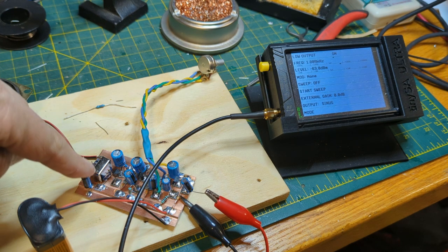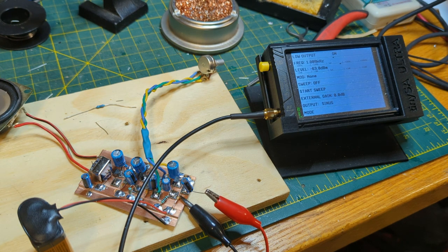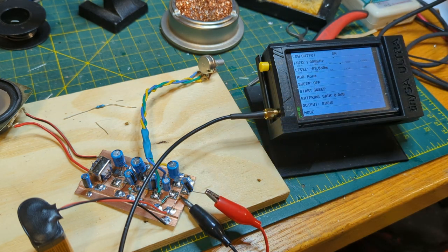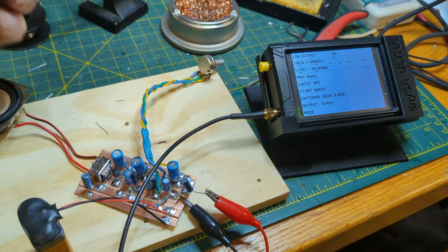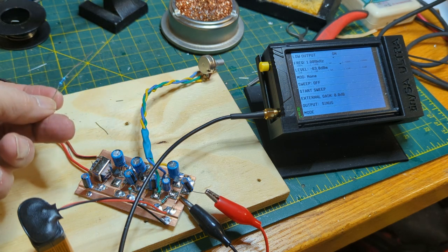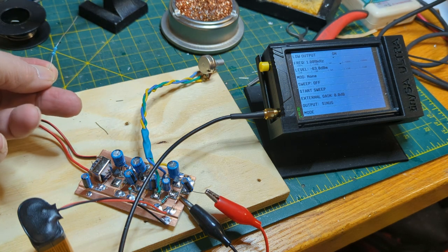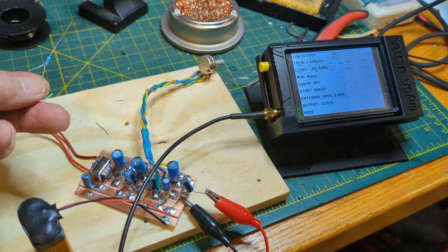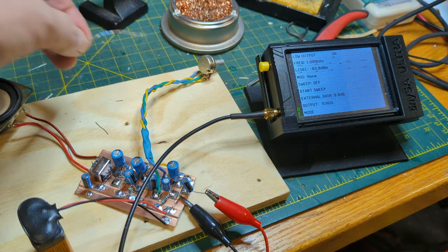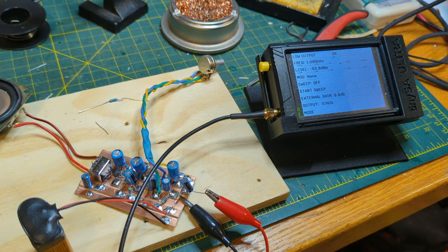Now I only have one of the DC bypass caps on. In fact, this is the other one here. I borrowed it for that temporary circuit. I may need to add another bypass cap. And then I've got that 220 ohm resistor that we talked about that was R20 on the schematic, which I may need to put in to knock down the input from this transistor, but I'll see what happens after I get it hooked up into the receiver and start listening to it.